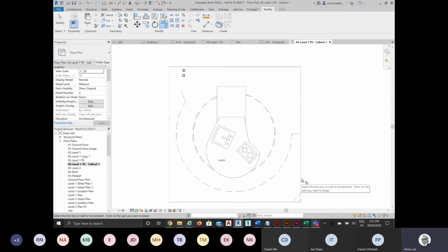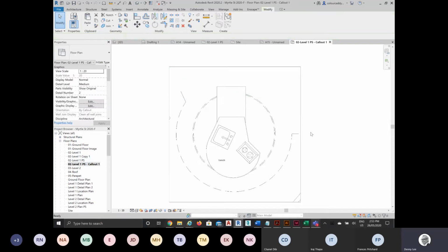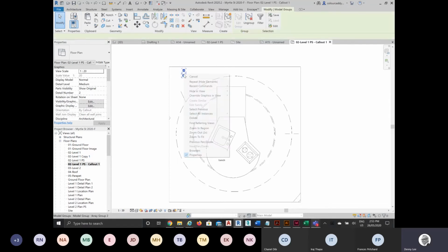Okay, now this is where it's weird. If you do it a couple of times, sometimes it will break it for you. In other cases, it will give you a message telling you that you've got to do it yourself. So it's important that you know how to do it manually, even though, again, sometimes the trim tool will do it for you. When I hide those things, I've just done an undo, but I've got to hide these again.